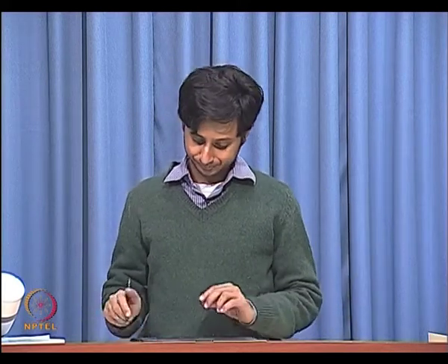If you go beyond this, if you make loops that have larger bandwidth, loop filters that have larger bandwidth, then unfortunately this approximation that we made over here is no longer valid. Once the approximation is no longer valid, then you have to work out the dynamics of this phase lock loop with greater thought. The problem is that at some point you have to do a conversion between discrete time and continuous time systems, and the complexities of that are going to be much greater. So, it is going to go beyond classroom teaching. So, this approximation works when the loop bandwidth is less than a tenth of the oscillation frequency. All right.